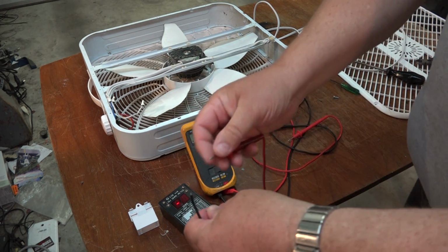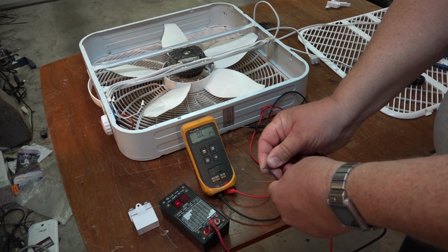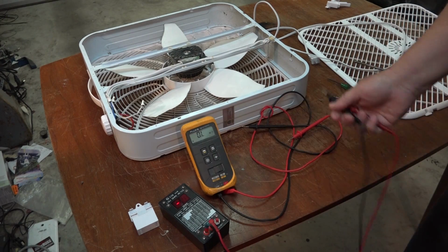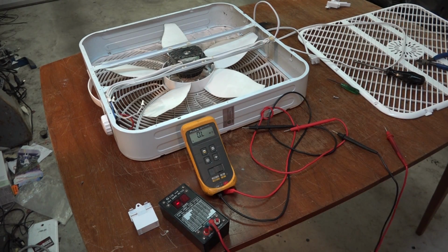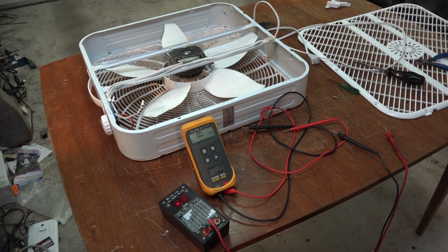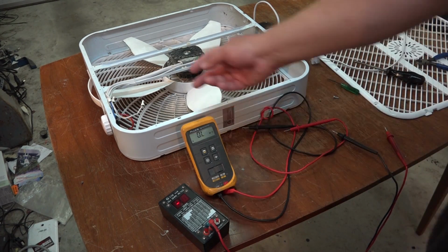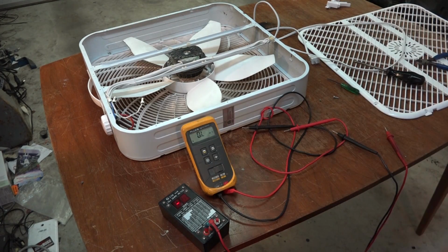Okay, here's the old capacitor. It's open. Completely open. No good. Okay, let's get the new one. And we'll put it back in here and see what happens with the fan. It'll fix it. I'm guaranteeing that this will fix the problem, because there's really nothing else to go wrong other than a motor bearing, which we know isn't the case because it spins. So I'm going to just get my heat gun out here, and we'll get some heat shrink on it. We'll heat shrink that on there and put this thing back together.